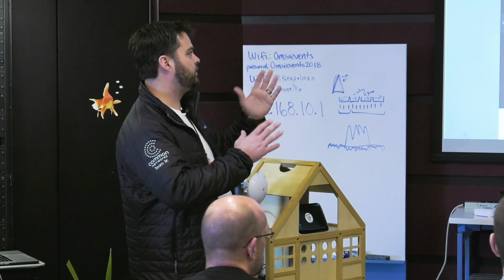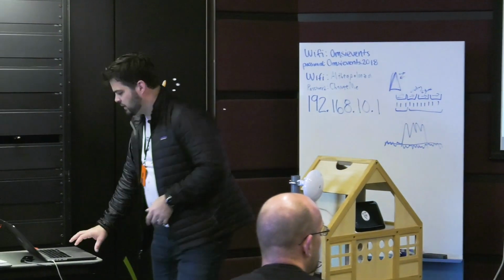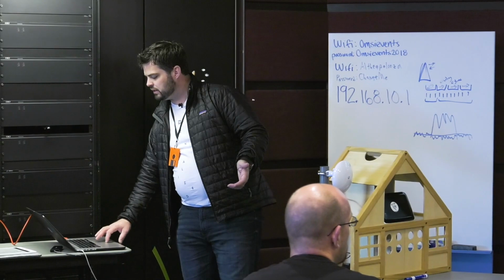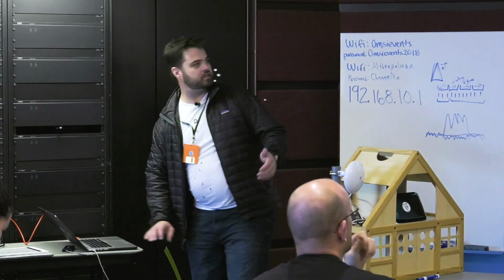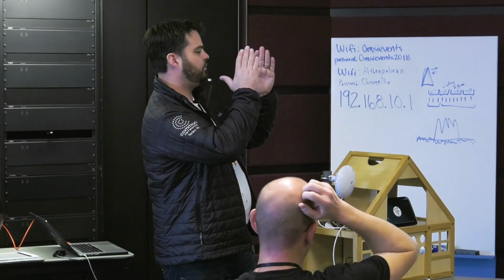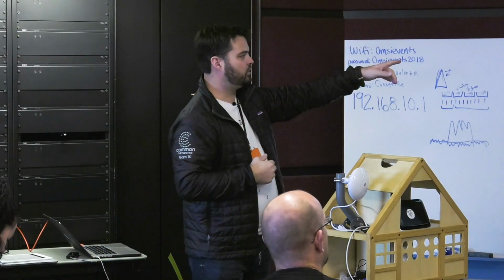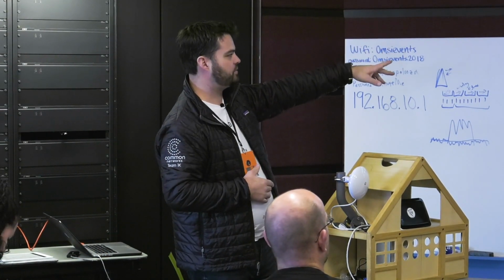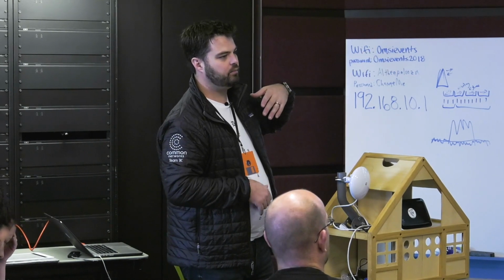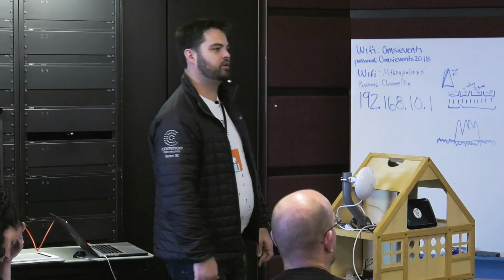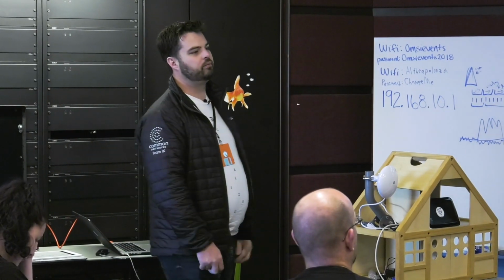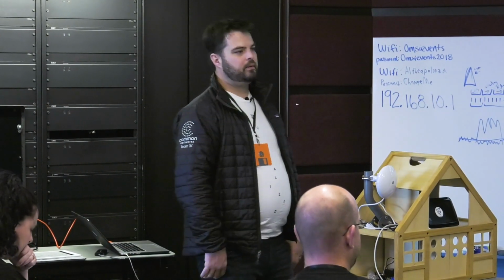We'll look at a few more. The other thing, if you really can't do guy wires, is to build a tower like this. That's just a tiny picture, but you can tell that it's angled. It's more of an A in this particular type of tower, and that will wobble less than the straight up tower. Does that make sense? You can purchase these from Rohn, I think, and other companies make this kind of tower. So if you can't use a guy wire, that might be better. Good question.